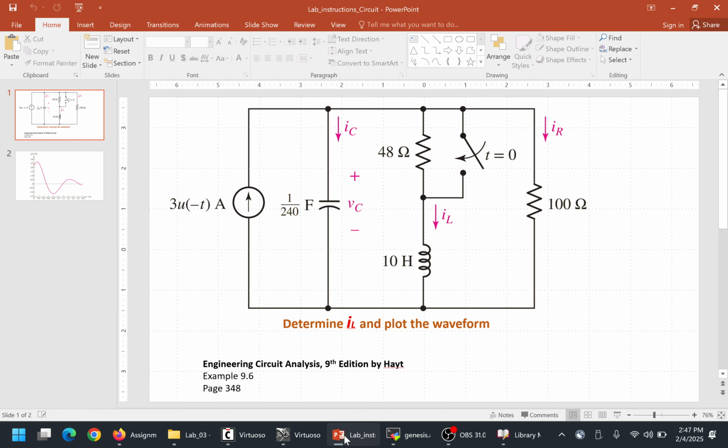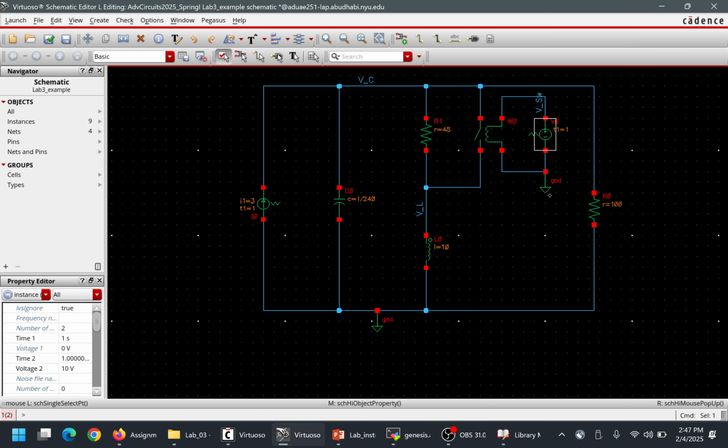Yeah, and this type of switch only closes when we provide the voltage, right? Yes, because look at this. This switch is normally open. If you see that, this is a normally open switch, so it will activate at a voltage. It is showing you its current condition, which is no voltage. Understand? You might have a switch that is closed and becomes open when you apply the voltage, right? Did you get the idea?